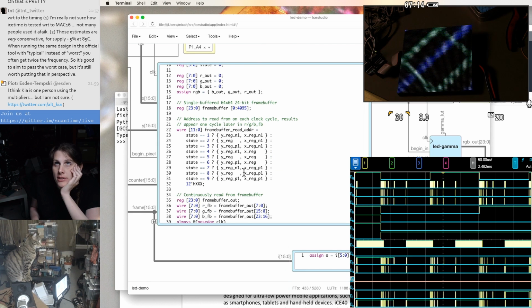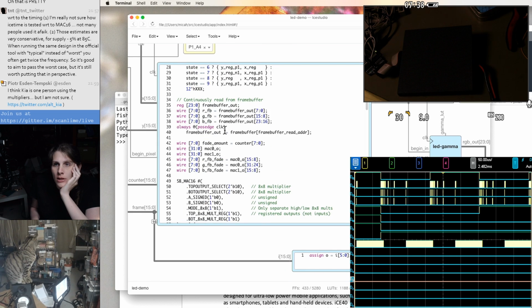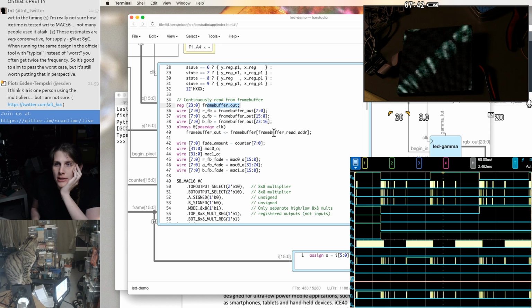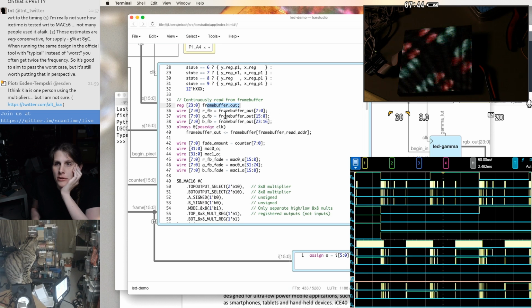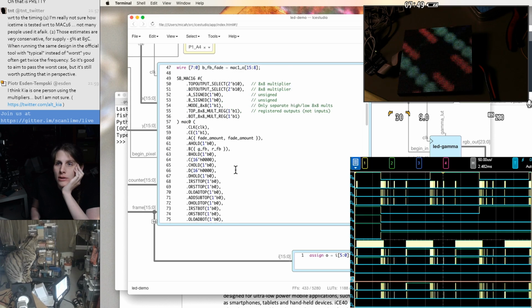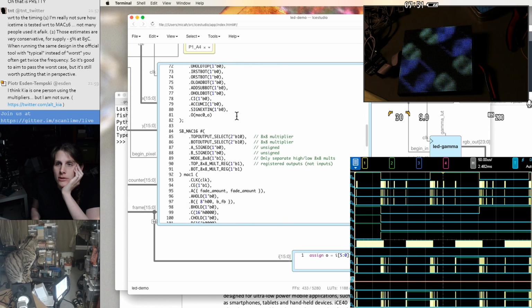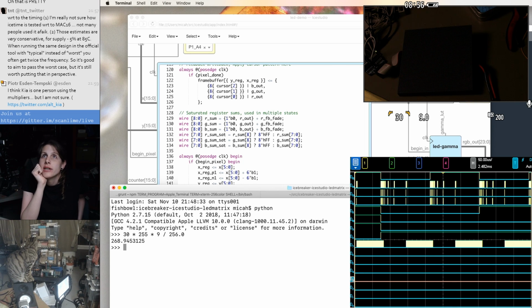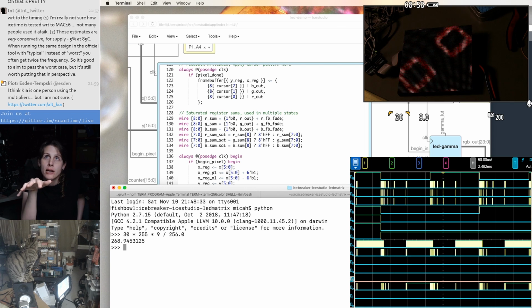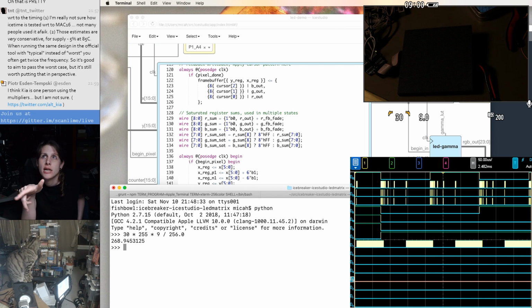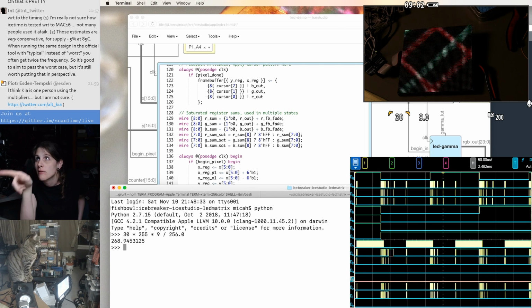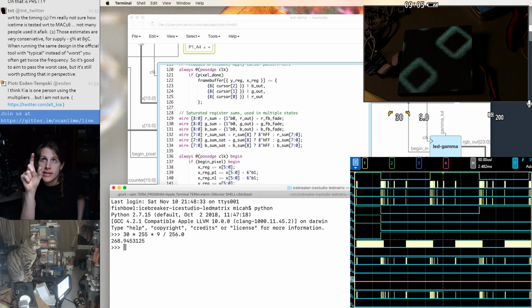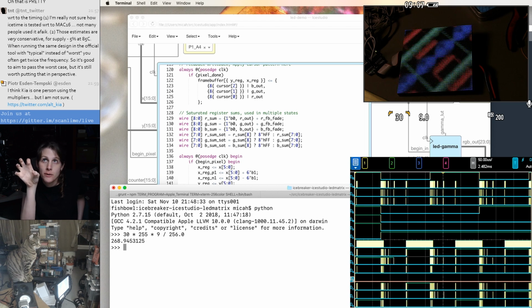So we're sampling these 9 locations. The results from the sampling go right into this register, which is actually like these 3 registers, RFB, GFB, BFB. Those get multiplied by this fade amount. So that is still slightly higher than gain of 1. So what this is doing right now is it's kind of striking a balance in how much it's attenuating these values as it sums them together. So for every pixel in the frame buffer, it's taking a neighborhood of 3x3 pixels around that pixel.